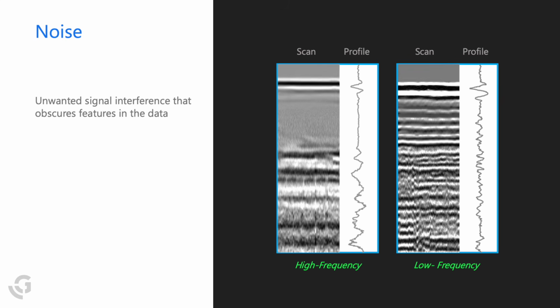With low frequency noise, we may encounter a subsurface material that's overly saturated, causing this banding effect all the way down our signal from the data. By using background removal, or the band filter, we're taking each individual scan and anything that repeats horizontally is removed, thus getting rid of this horizontal banding that's otherwise obscuring our targets.